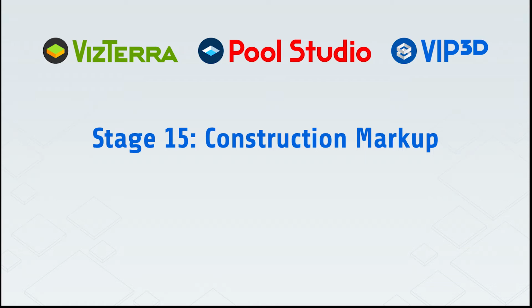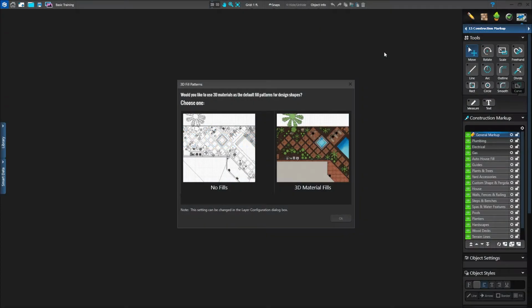This video will explain Stage 15, Construction Markup. In this stage, you will add guides, callouts, plumbing and electric lines, and set the line and fill styles for your construction plans. The first time you enter Construction Markup, a prompt will ask if you'd like to use 3D